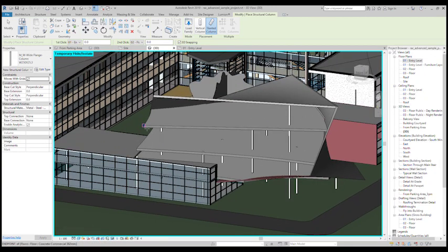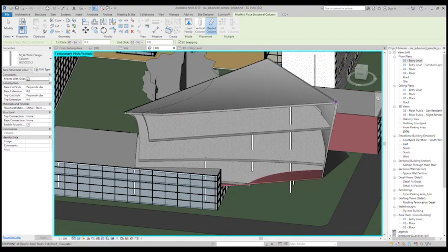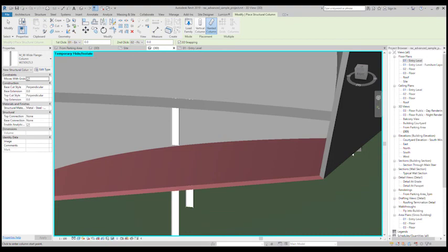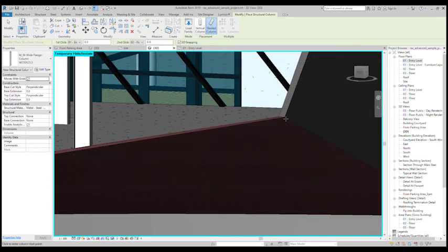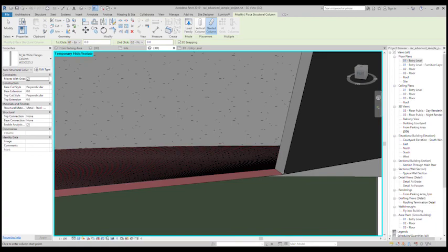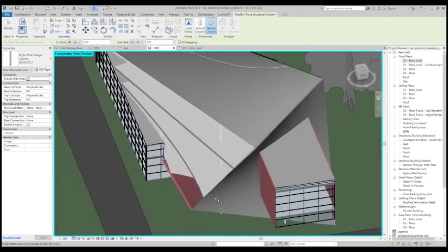But with floors, you can only select corners. Roofs the same. And unfortunately, it doesn't snap to walls. That's actually snapping to the roof there. It won't really snap to walls. You can see where two walls come together, it's actually a really neat join. You can't snap to them, which is unfortunate.